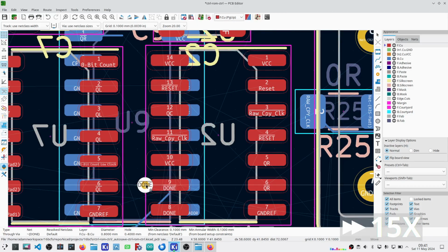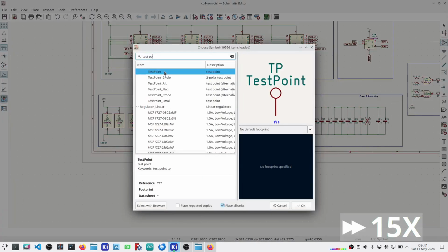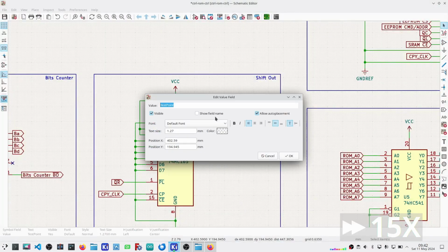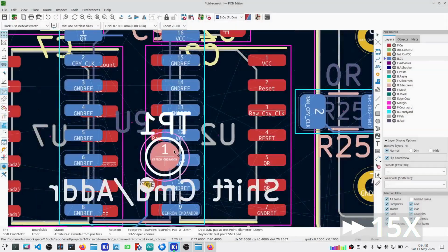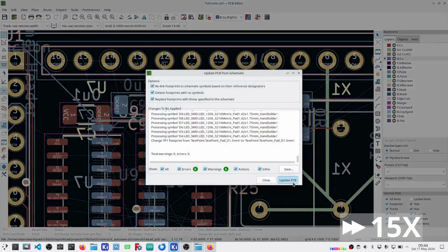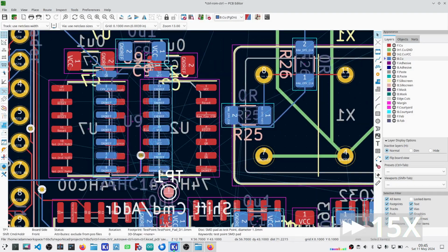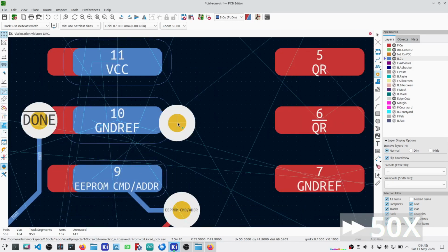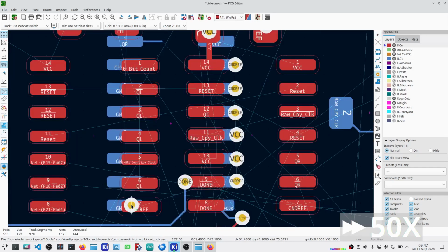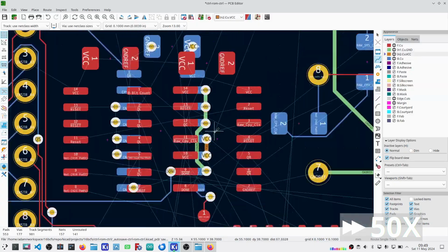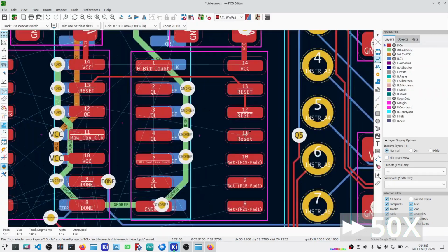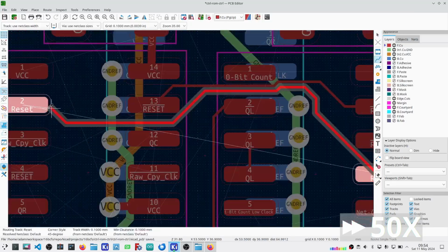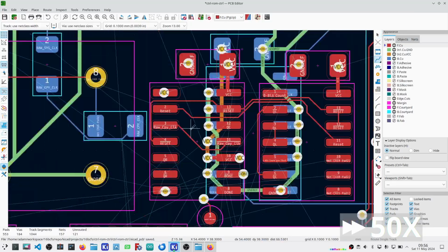And my done thing here is not going to be in a good spot. Now it's time to set up that test point. I want to bring the command address signal from the shift register up onto the front of the board. Okay, then it's just the final push to get the rest of everything routed. It's not the best job I've done. I ended up having to get a little creative as I'm going through trying to route some of these signals, but it did eventually all fit.